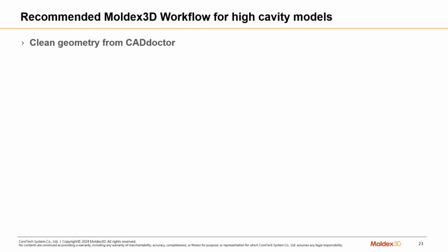First thing I need to do is clean the geometry from CAD Doctor. As you can see, CAD Doctor is going to do all the heavy lifting of cleaning up the mesh and the geometry. So when you have the geometry ready, the STEP file, bring it inside CAD Doctor, clean it up, make sure it's ready to go, no issues or errors. CAD Doctor is so powerful; it's going to automatically help you fix any minor issues on the CAD side.